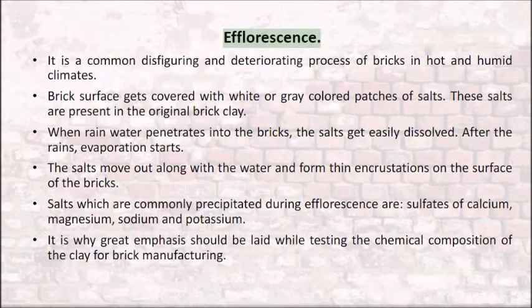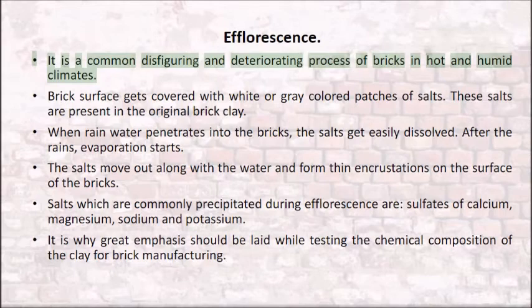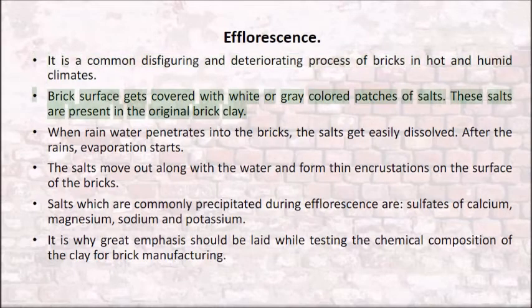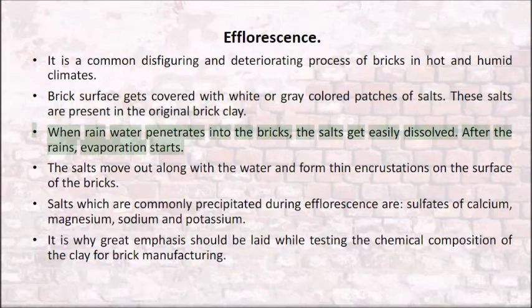Efflorescence. It is a common disfiguring and deteriorating process of bricks in hot and humid climates. Brick surface gets covered with white or gray-colored patches of salts. These salts are present in the original brick clay. When rainwater penetrates into the bricks, the salts get easily dissolved.